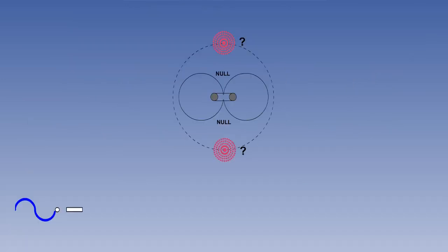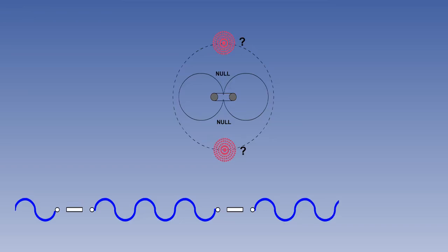This brings us to an end of the 2 lessons on the NDB and the ADF. In the first lesson, we looked at the principle of the loop antenna and the position of the 2 null readings, and how this ambiguity is resolved with a sense antenna. We considered the operation of the goniometer, which has replaced the moving loop antenna, and we have looked at the emission characteristics of NDB transmissions.